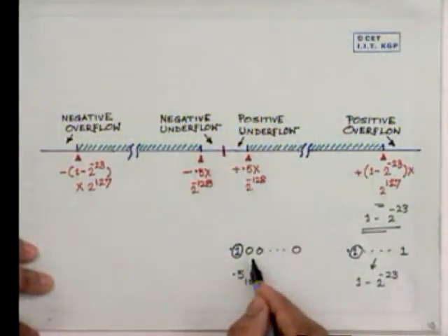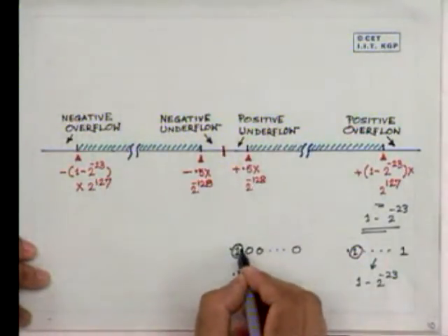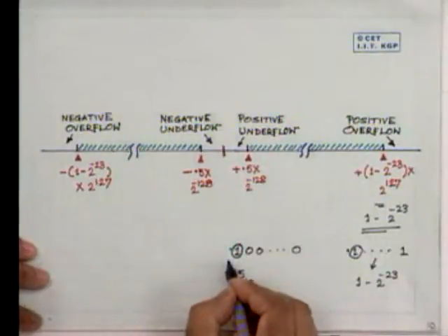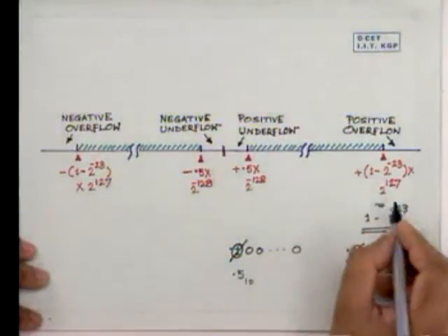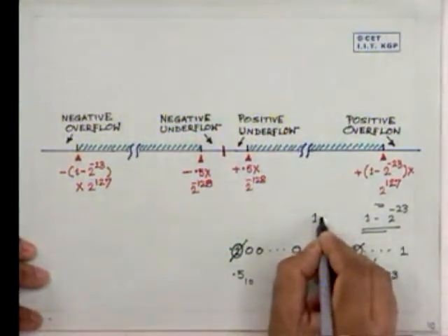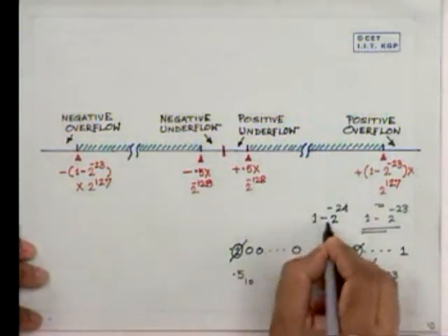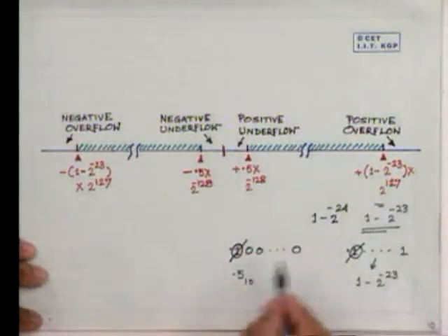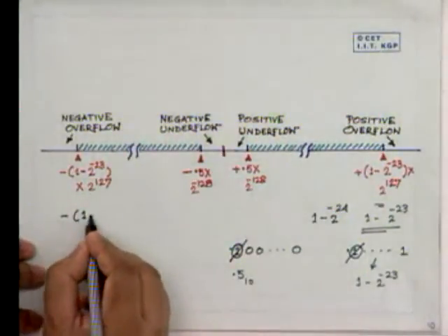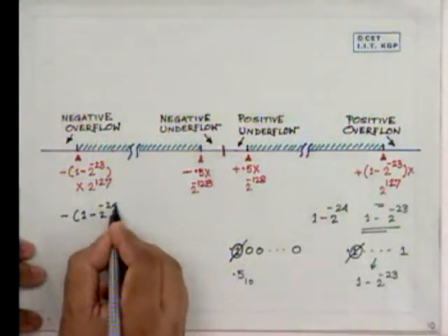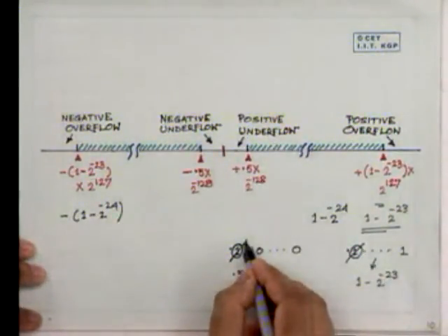Now, since we know that the most significant bit after the binary point has to be 1, we may not represent it here. In that case, we can go up to 24 bits, and we can have a number represented up to 1 minus 2 to the power minus 24 on the positive side, and also on the negative side, since this bit we know will always be 1 and need not be represented.